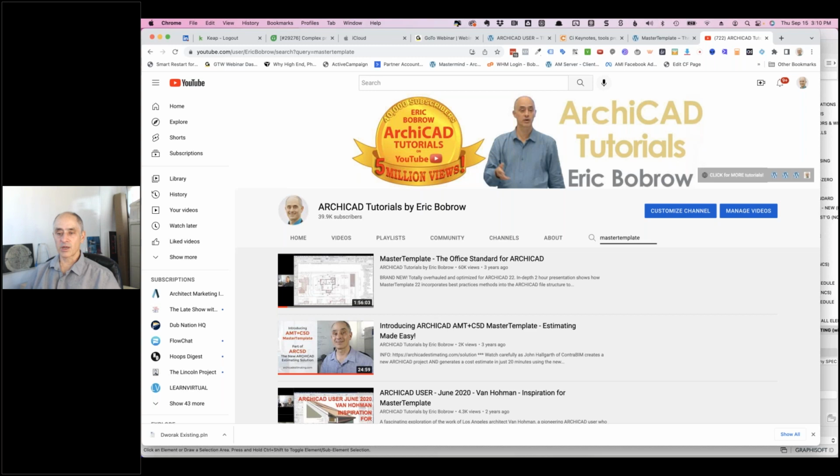Yeah, the criteria that say it's not a beam segment or not a column segment. It's migrating, maybe because the text field is blank. No, I think I explained that. That was basically you couldn't fill in some information because the field reference was unavailable. So there's something in the schedules that says you can type in things if the element you're referring to has a placeholder, a place to put it. If it doesn't, then you'll see 3 dashes, and it'll basically mean I don't have that information, and there's no place to put it.